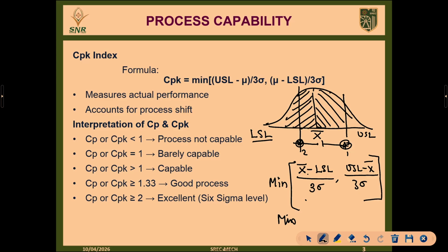When you consider point 2, it is a little closer to the central point when compared to point 1. The process seems to be stable. Suppose we are not taking any corrective action, there is a possibility that point 2 will move towards the left and it will reach the lower specification limit and go beyond that. So to avoid that, we have to check what is the deviation from the central location. If you find the location deviates from the central position, we have to take corrective measures so that we can bring this process closer to the central position to make the process stable.